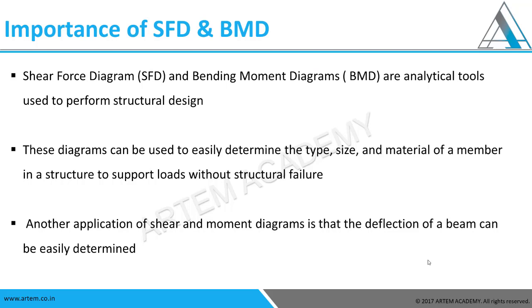Now let's discuss the importance of SFD and BMD. Shear force diagrams and bending moment diagrams are the analytical tools used to perform structural design. For designing, SFD and BMD are actually very important. They give us an idea of how much load the beam is taking and what dimensions we have to take. So it is very essential for us to know. These diagrams can be used to easily determine the type, size and material of a member in a structure to support loads without structural failure.